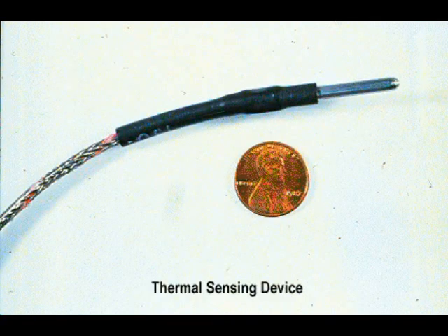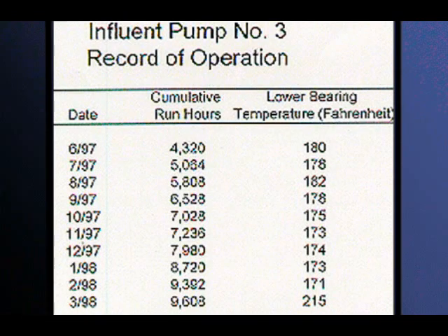Bearing temperature should be monitored. On larger units, automatic systems may shut down the pumps in case of high bearing temperatures. These systems have temperature sensing devices installed like the one pictured here. Readings of the bearing temperature should be taken monthly. A good recording system of these readings will provide warnings of bearing problems.